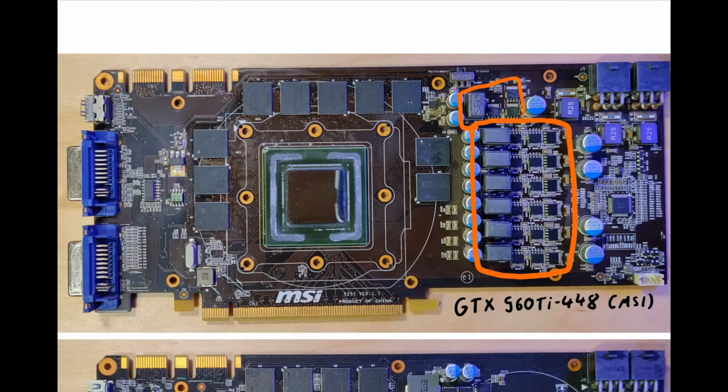So let's get back to the basics again. So here we have vMem, and then we have vCore. The V stands for voltage, because the VRM supplies your voltage and your power that you need to drive your graphics chips and all the other things that make calculations on your graphics card. So vCore, pretty obvious from the name, goes to the core of the card, the GPU, and vMem goes to the little memory chips on the card.